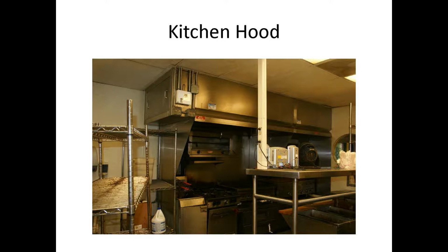Sometimes it can be pre-cooled, but you have to provide almost as much makeup air as the exhaust that's going out. Otherwise, the building would be very negative. It would suck all the air conditioning out of the building, and nobody would be comfortable. So it's called balancing the building. And that's another thing we do in HVAC design.